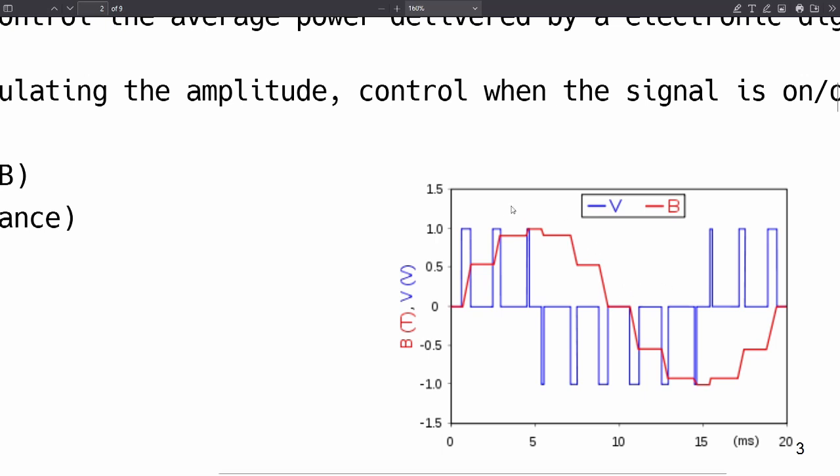What is another possible reason for why we only want to have voltage high and voltage low? Okay. Yeah? It's a digital system. Sure, it's a digital system. So our peripherals, for the most part, also only expect voltage high, voltage low. Even LEDs are configured to work best when you feed them an exact voltage and an exact current. And if you now feed them half the voltage, what's going to happen is it probably just won't turn on at all. Or if you give it half the current, maybe it just won't turn on. If you give it twice the current, it'll burn out.